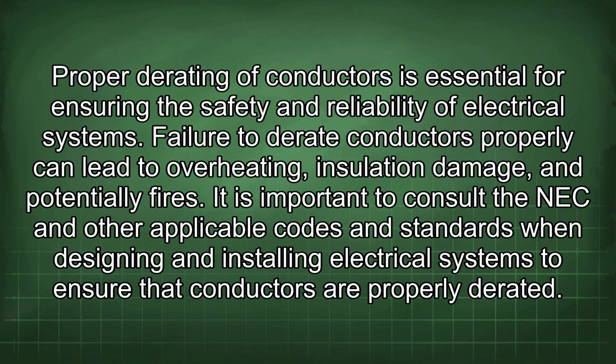Proper derating of conductors is essential for ensuring the safety and reliability of electrical systems. Failure to derate conductors properly can lead to overheating, insulation damage, and potentially fires. It is important to consult the NEC and other applicable codes and standards when designing and installing electrical systems to ensure that conductors are properly derated.